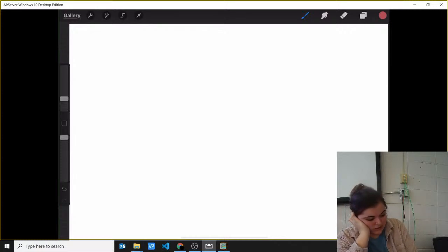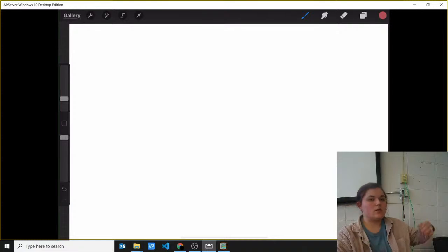It is a method in which the programmed deceleration time is doubled and the stop function is changed from a ramp slope to an S-curve slope. So the soft stop method provides a very soft stopping operation. A very soft stop may be required to prevent light loads, such as empty cans or bottles, from tipping. So that would make sense.